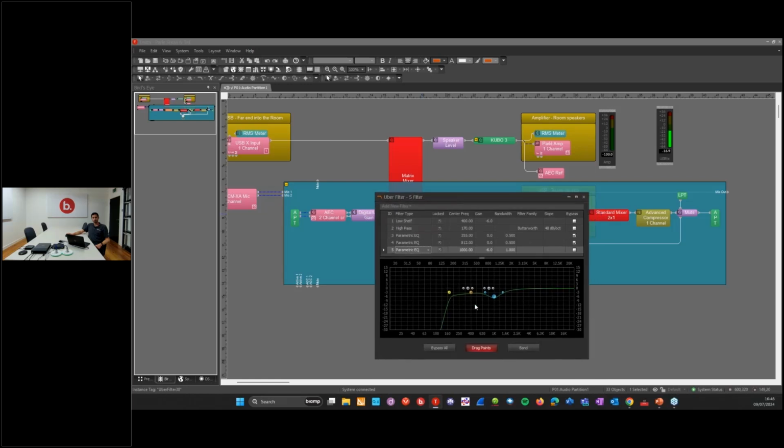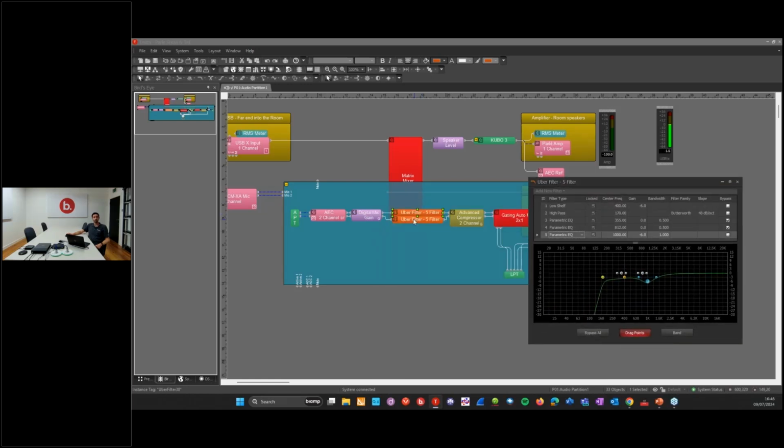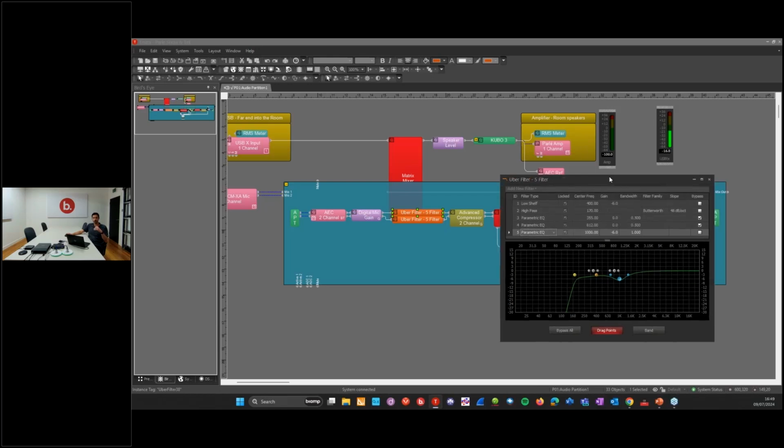And then we have the filters. They're all the same no matter how many channels you have here, and generally they follow a certain paradigm. You take off the very low end of the microphone. The reason being is the larger the mic is, the lower you can track down to. So there is a limit to how tightly you can form beams at low frequencies. So we tend to take off a bit of the bottom end so that we don't get that low frequency build up within the mic. And then you see there are just general, quite broad stroke filters here.